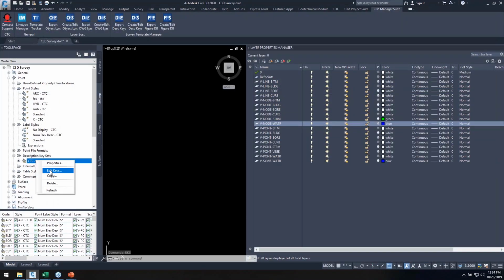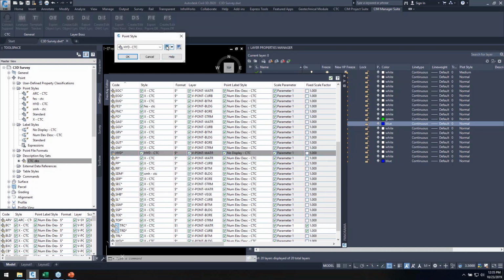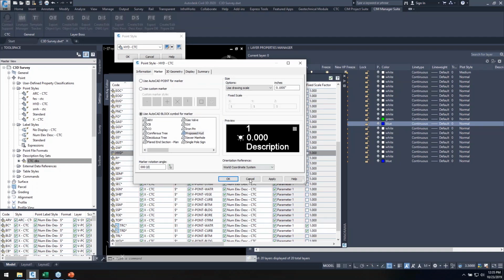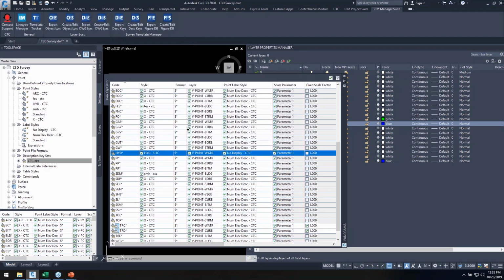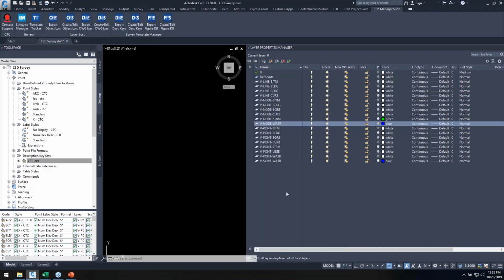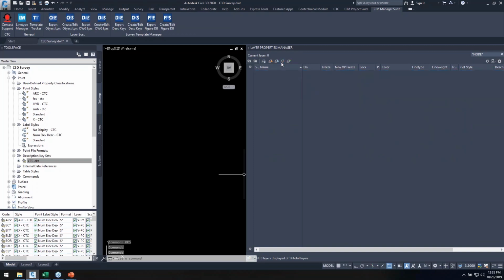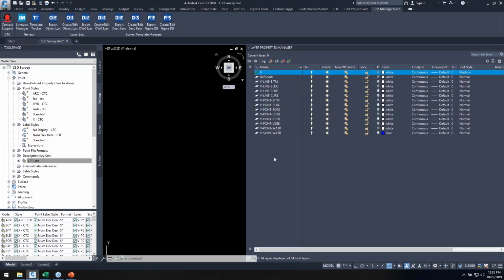And if I look at the description key set again, we're going to see all those updates pushed. So all the layering has changed. There's that hydrant code with the hydrant point style. And of course, inside the point style, it's referencing the hydrant block. Then in the layering, of course, what do I get? Well, now I have some node layers, pretty simple to deal with. Just delete them out of there. Nothing's using those layers anymore. And now I've just converted my whole layering standards.